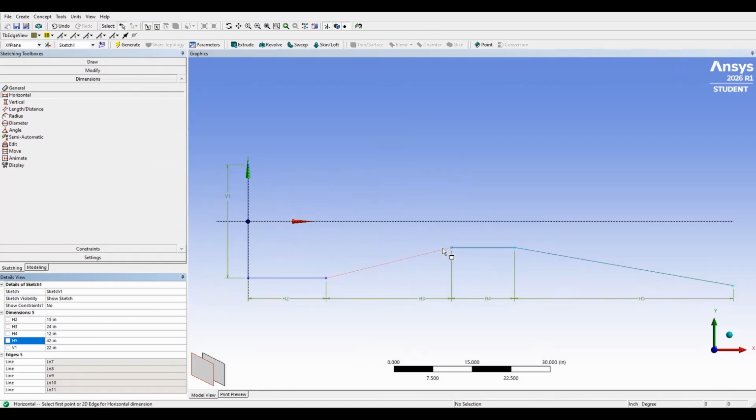Because we have this center line right on the x-axis, and this is only half of the 2D wind tunnel, that means the height of the test chamber, which we are given at 6 inches, is actually only going to be 3 from here to the mid or x-axis.